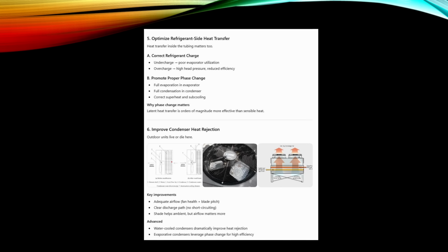One important question is, of course, how our condenser unit is working. When you locate this condenser, be careful that the air is not recirculating, so you will always have very good behavior and performance in this unit.